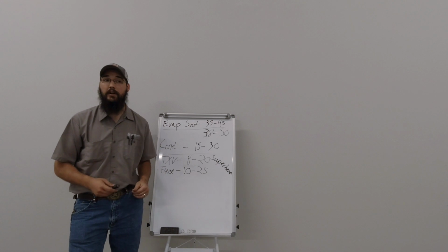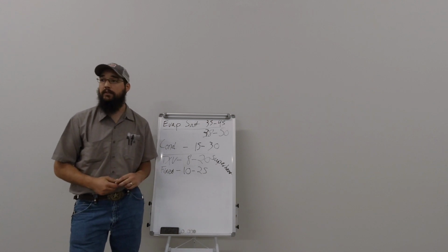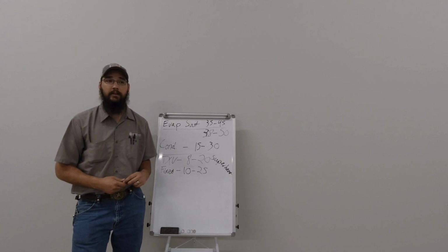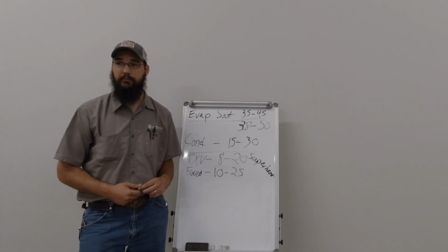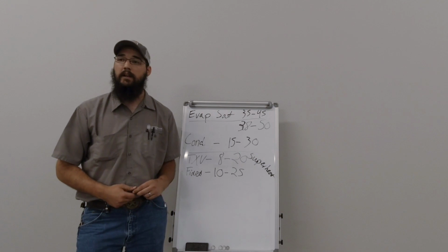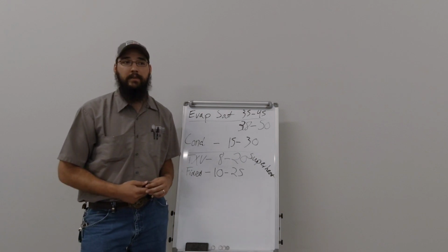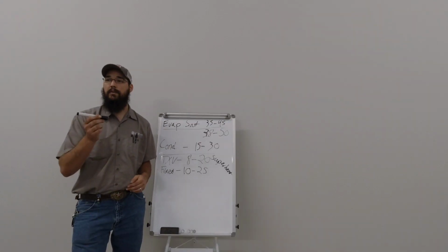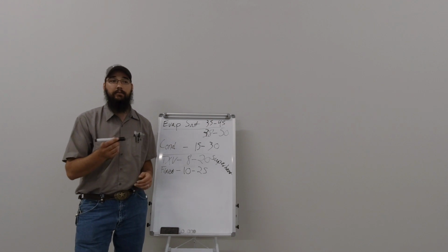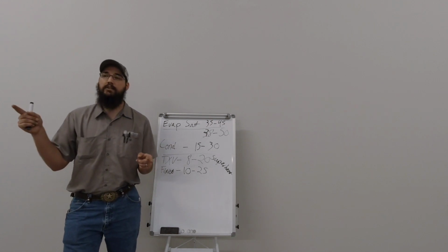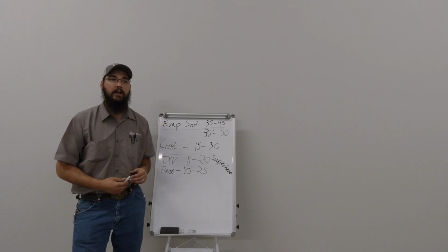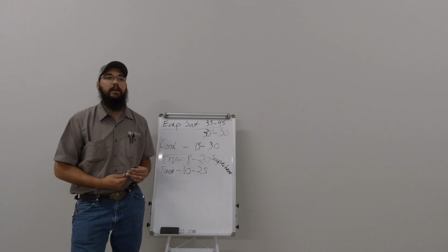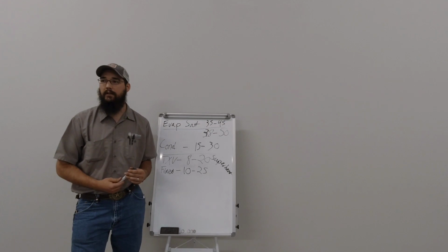This was a real scenario. At an account, they kept throwing compressors. They went through 3 of them before I got there. Whenever we did the last one, this was the procedure we did, and they were very much not in calibration. And that's exactly what was happening. The moment it would stage up, it would be fine by itself. Heck, it was okay-ish with the other compressor. The moment both compressors ran on the same circuit, that superheat wasn't even there. It was just a straight flood back.